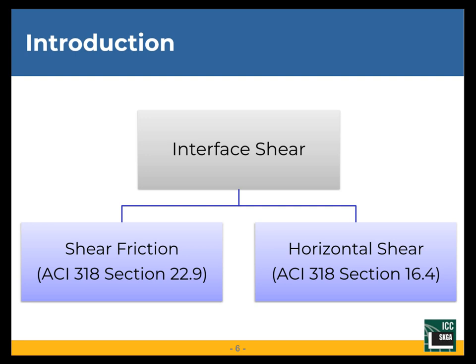The demands you're designing them for differ a little bit, and the applications where you would apply the provisions differ. Of course, horizontal shear is intended for a horizontal plane, but the concepts are really the same in the way that the force is transferred across that interface, whether it's cracked concrete, two concretes cast at different times, or whatever that interface is created from. So in general today, I'm going to refer to interface shear, but there will be some aspects of both shear friction and horizontal shear that we will be talking about.